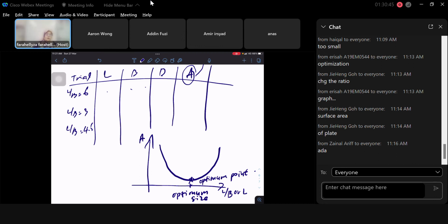Yeah, but for most of your friends from SEMO last time, for main dimension, I asked them to not go too detailed. As long as you do some iteration process and you change one or two ratios, like the L upon B ratio, that should be enough. So that's how we solve the design process as a ship designer or a naval architect.